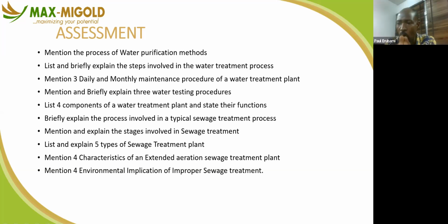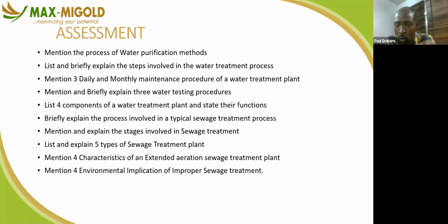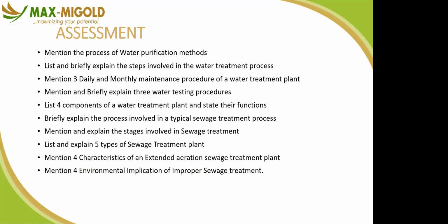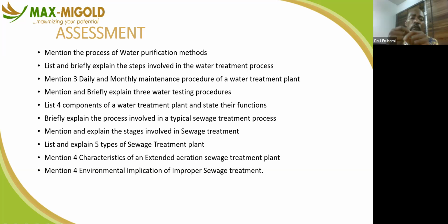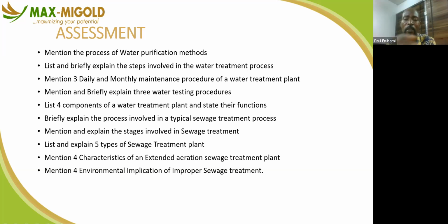The reason why you are compressing the borehole is that there is something we call the screen. The screen are pores, holes where the water from the ground enters the borehole column. At times, jets can clog those points. That will reduce the influx of water into the column, and once there is a reduction in the influx of water, your submersible will have less water to take out. So what you do by compression is clear all the pores, all the holes on the screen, so that you have much more influx of water into the column of your borehole.